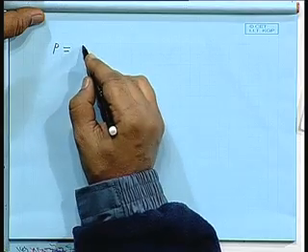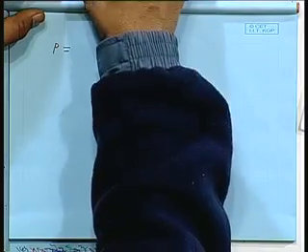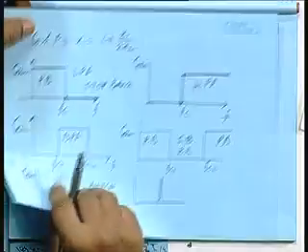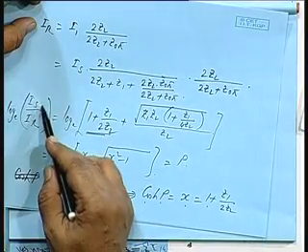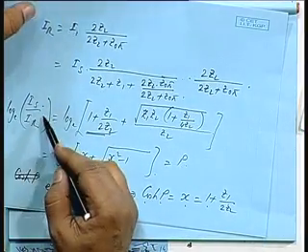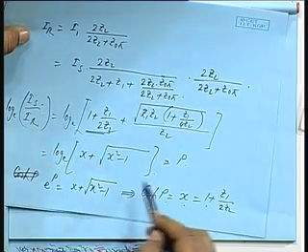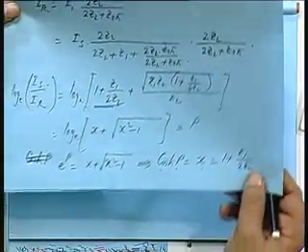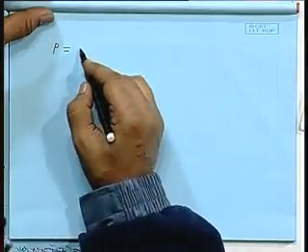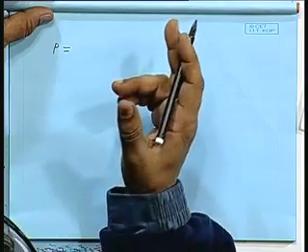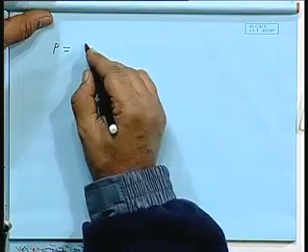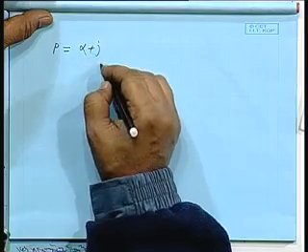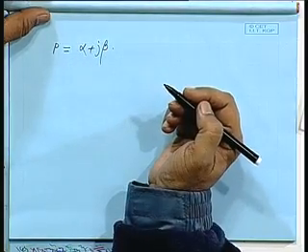P may be a complex quantity. When you are taking the ratio IS by IR in a complex network, this may have a phase. So, the logarithm of that also may be a complex quantity, meaning the current magnitude changes, and its phase is also changing. So, let that complex factor be alpha plus j beta.